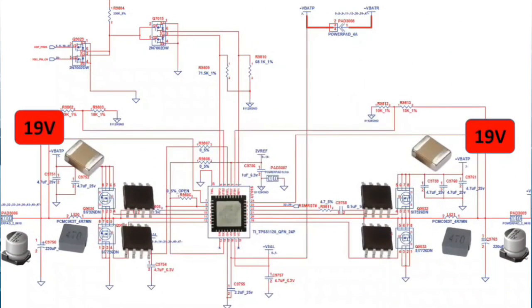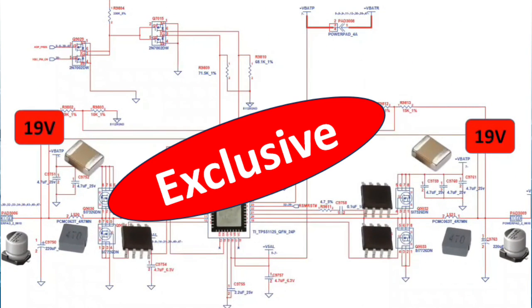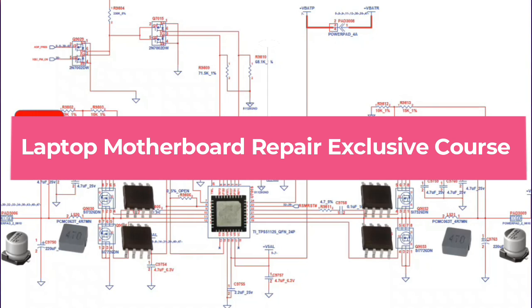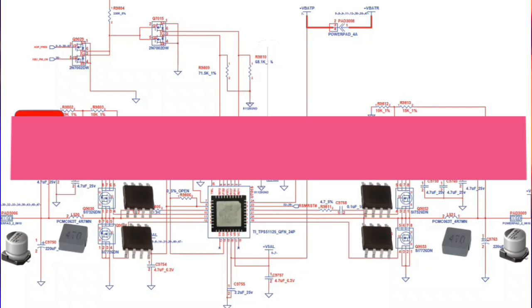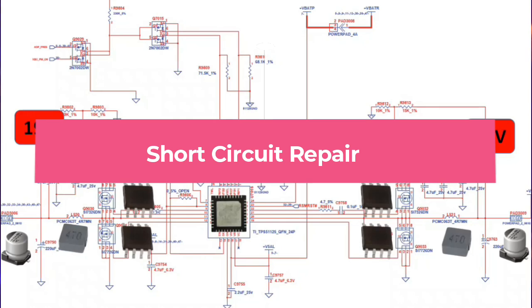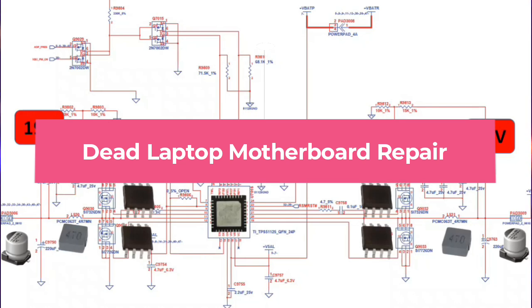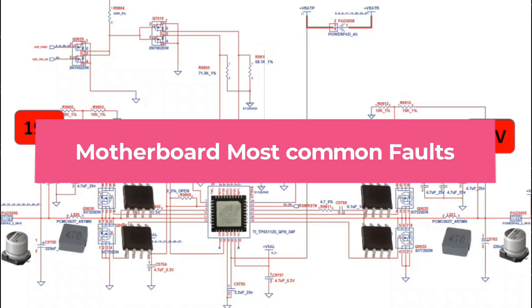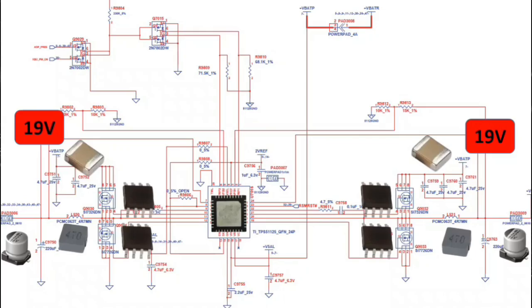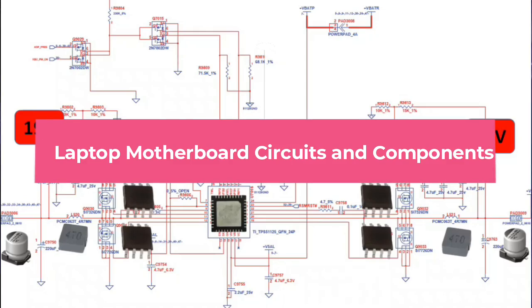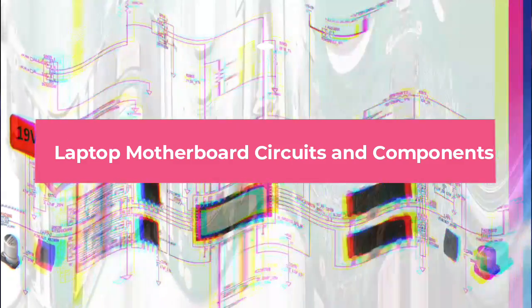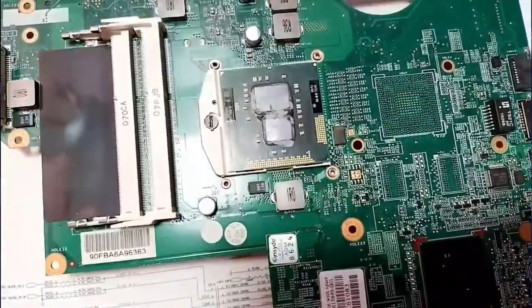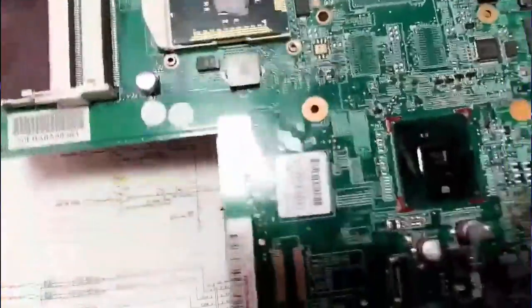This is a very exclusive video where you're going to learn everything about how to repair laptop motherboards, including short circuits repairing, how to identify the cause of dead motherboards, how to trace the voltage, the most common fault on a failed laptop motherboard, and of course you're going to learn the components that compose every circuit in the motherboard. So the first thing to do is a visual inspection.